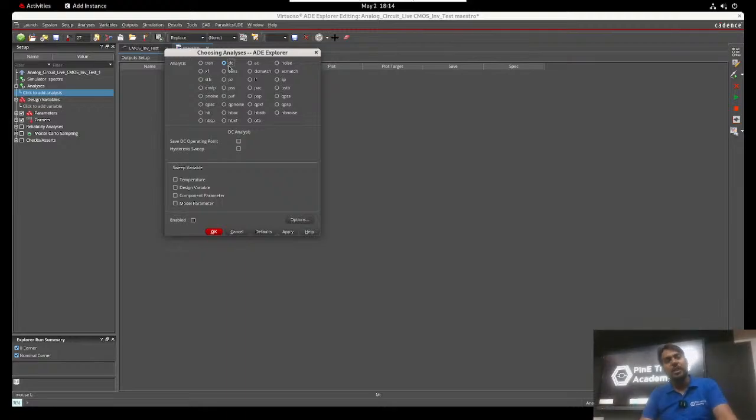Last class we discussed the different types of analysis: transient, DC, AC, noise, stability. Transient will help you define the delay, rise time, fall time, everything related to time that will be simulated in the transient response. If you are interested in static power, that is DC operating point, DC analysis, static power, that will be related to the DC analysis. If you are interested in terms of frequency, you will go for the AC analysis. So these are the basic analyses: transient, DC and AC.